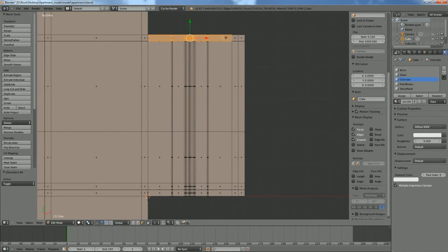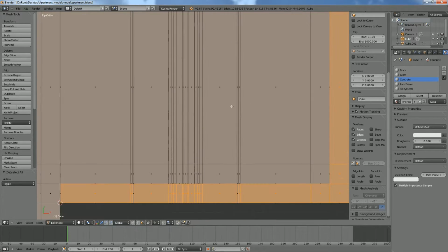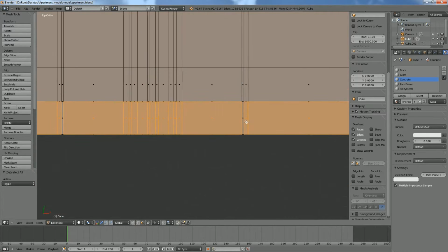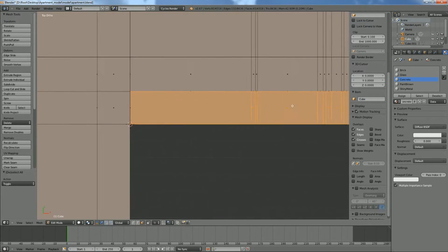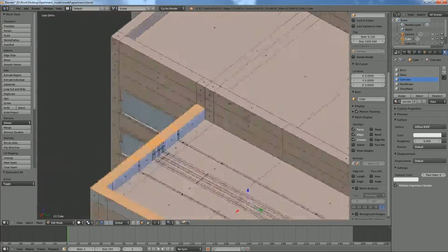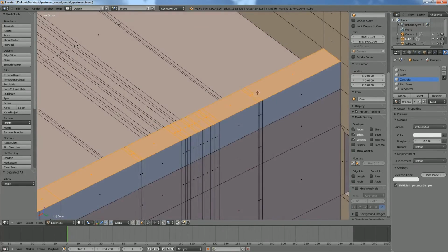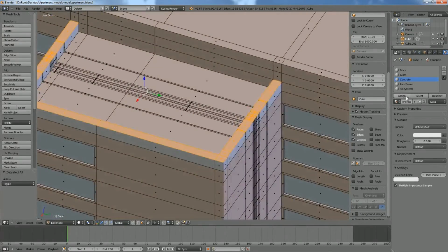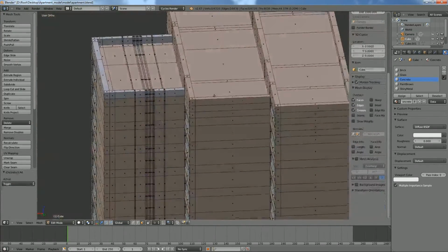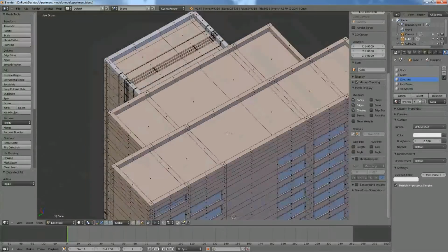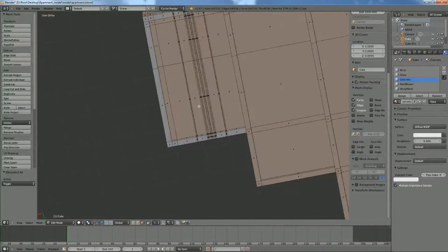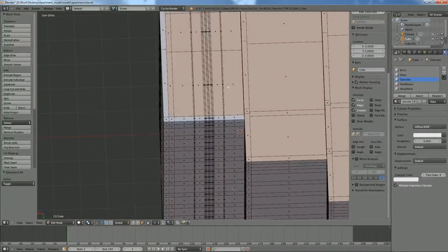Now, a limitation of the circle select tool is that it doesn't have very good resolution in denser areas, so you'll have to zoom in to make sure you have all those faces selected. Okay, and a couple more on this side. Okay, and we'll hit assign. We just want to do the same thing over on these as well, and we'll also be selecting this entire floor area.